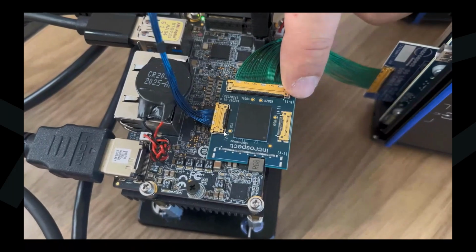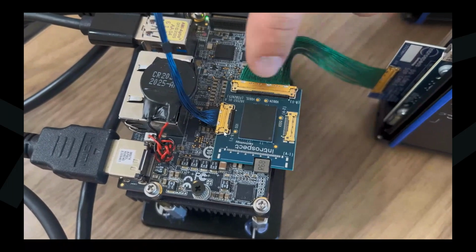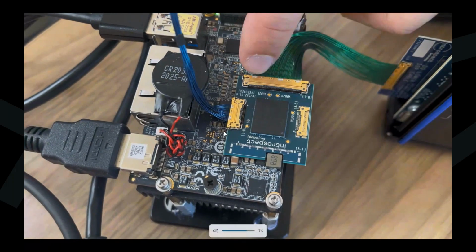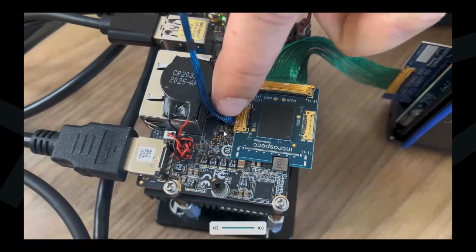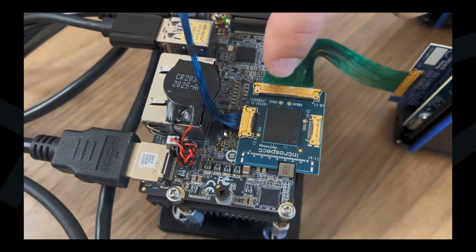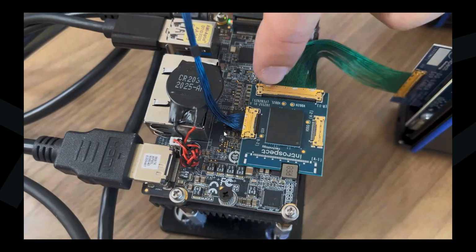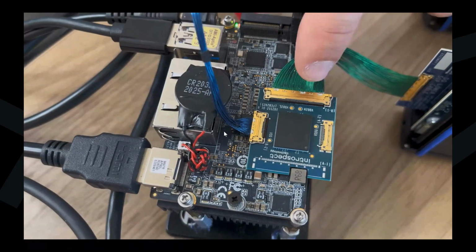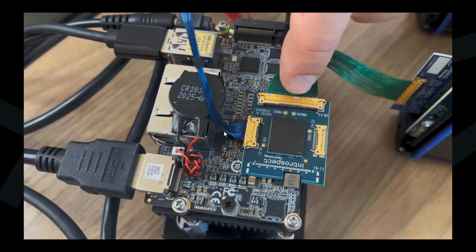This kind of interposer provides solderless access to all signals under the memory. So here we're showing the DQ signals in this green cable assembly and the CA signals in the blue cable assembly. And because it does not require any soldering and everything is embedded inside the connector, you get very high signal integrity and very low noise coming out of this interposer.